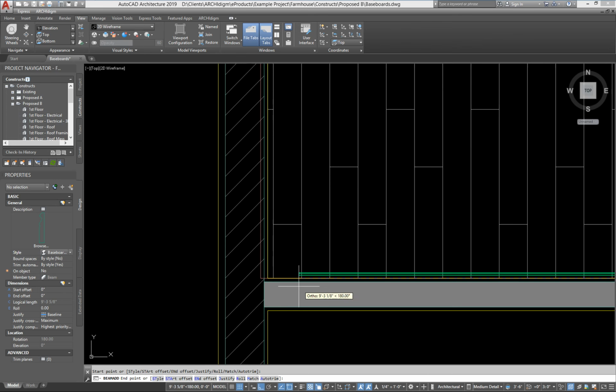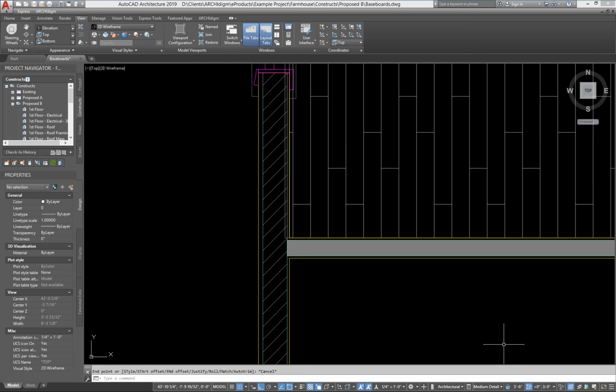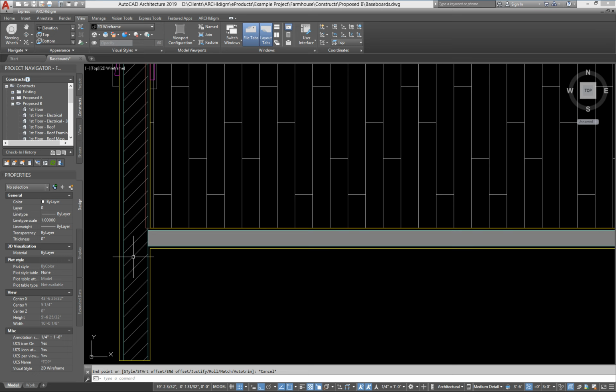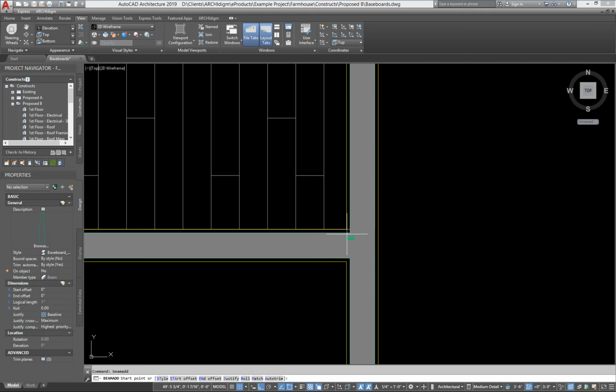And come down. You know, let's lock, this is a good thing to do, replace Z, lock that to 0 so that you don't end up hitting something that you don't want. And then I'll go ahead and beam add again and make sure this is set to no.